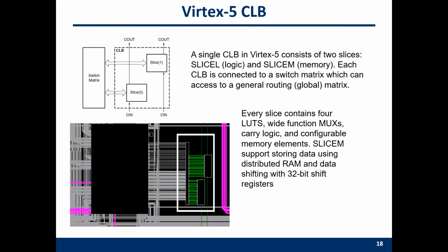Every slice actually contains 4 lookup tables, and the write function masks, carry logic and configurable memory elements. The slices used to implement the memory also support storing data using some distributed RAMs and a memory shift. This is enabled by some 32-bit shift registers.